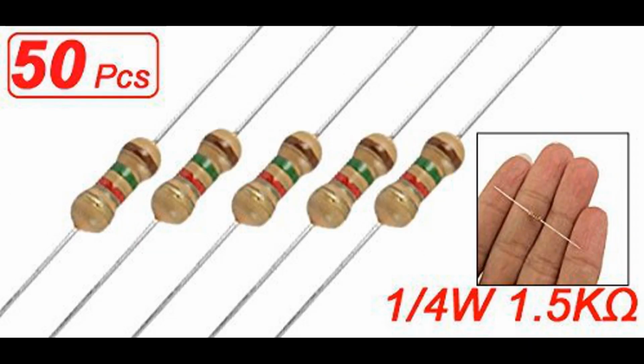Load resistors. Power resistors are used as load resistors in various applications, including power supplies and electronic loads. They help dissipate excess power and maintain stable operating conditions. Filtering. In passive filter circuits, resistors are used to set the cutoff frequencies and shape the response of filters, such as low pass, high pass, band pass, and notch filters.